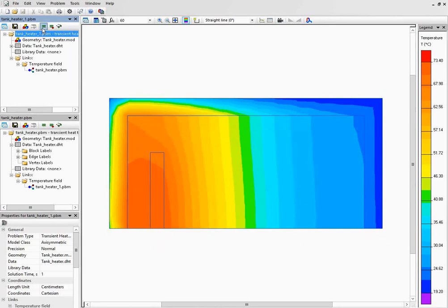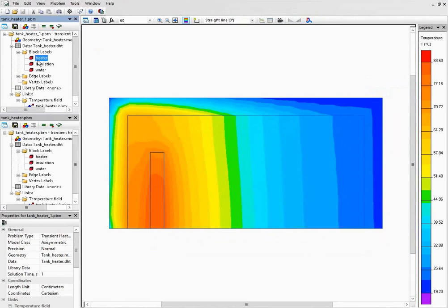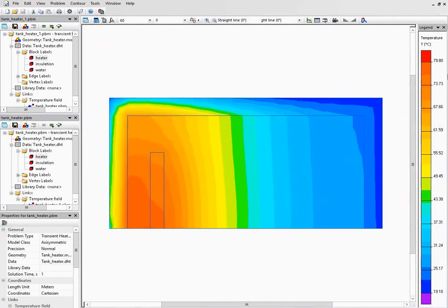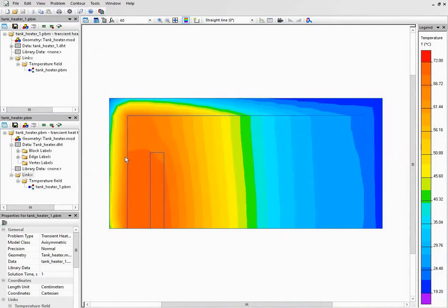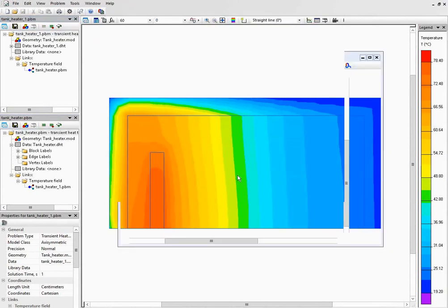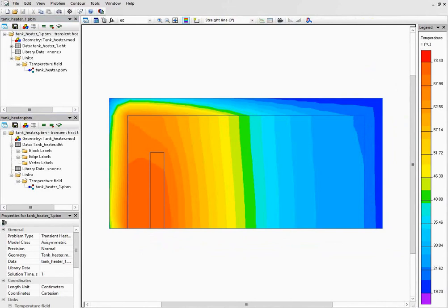So if I change the power source to be 0, run the cycle again. I will simulate the cooling process. And if we run the cycle again, we will model next 2 minutes of the heating process. Now we can build the control system. The control system will run and count simulation cycles, measure the temperature, and switch on and off the power source.